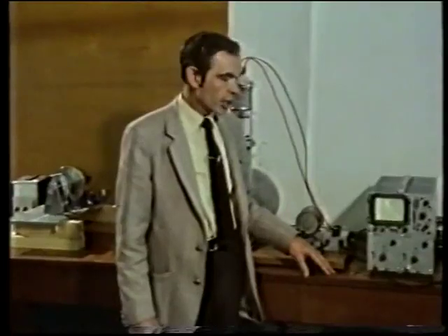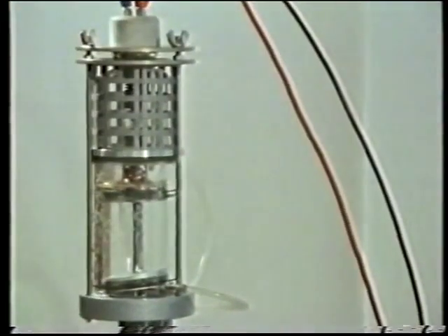We can have a further increase in power output by changing the gas from air to a light gas such as helium or hydrogen, which is more easily pushed through the regenerator from the hot side to the cold side and back. This allows us to operate an engine at high speed, high efficiency, and high specific output.